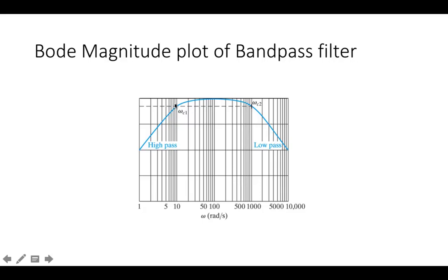Now the reason that's important is if you could visualize that we make omega C1 and omega C2 get closer and closer together, you can see how, at the knee, the cutoff frequency here and here, we're less than 1 on our gain. So if these 2 points approach one another, then what we have is this curve multiplying this curve in the middle, not where they've approached a gain of 1, but where they're down here below 1.